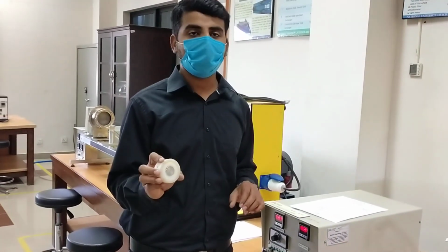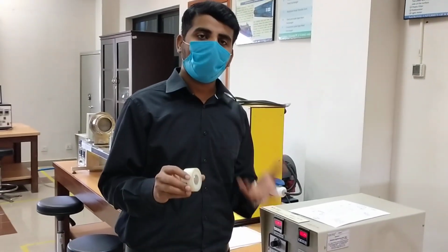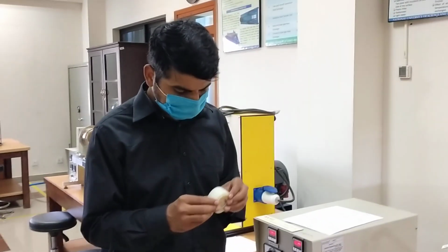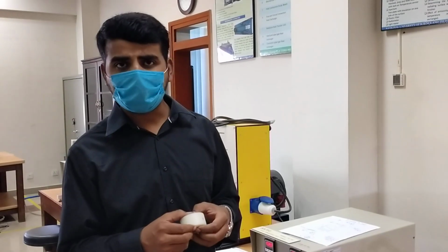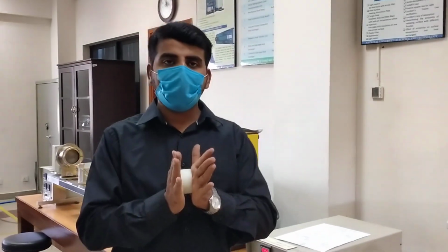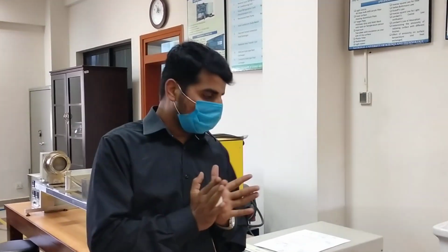And this one is made of stainless steel. This one is again 25 mm, and you can use it to find the thermal conductivity of stainless steel, but you have to make sure that it is tightly held between the heater and the cooling end to measure the approximate thermal conductivity of the steel.